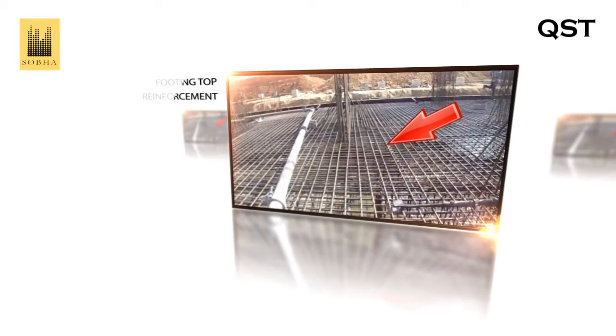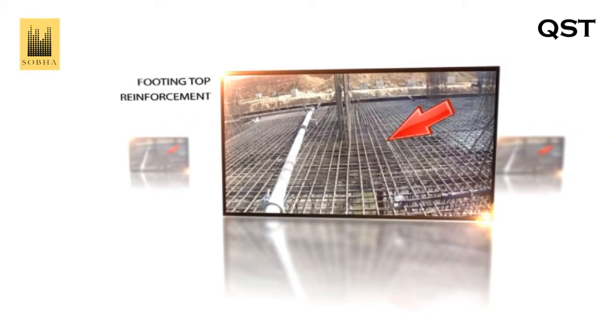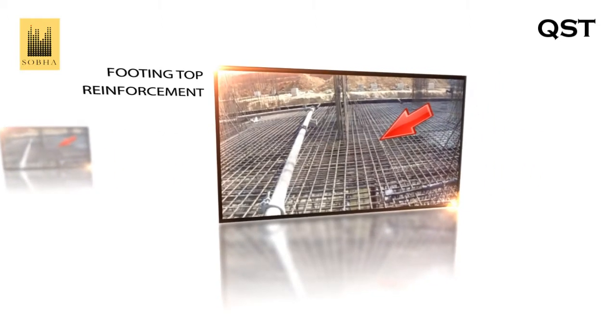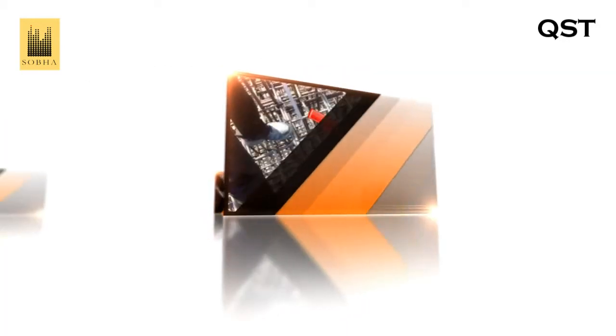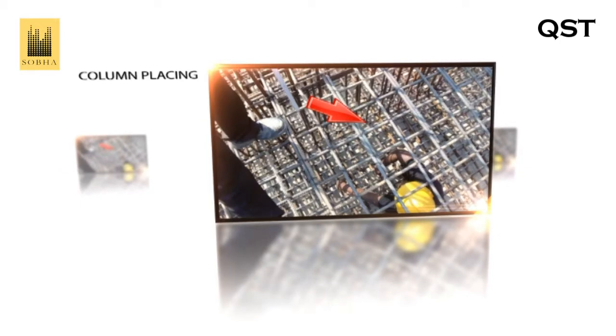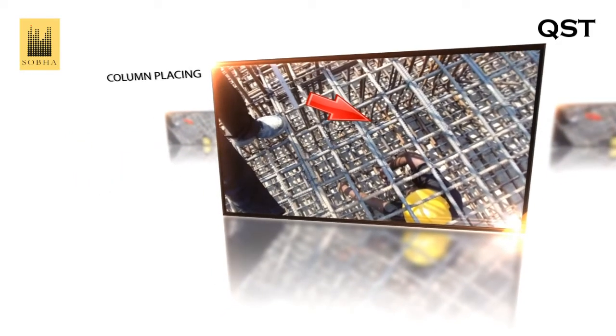Footing top mat. This image shows the typical picture of a footing top mat and additional rods. All works should be executed as per good for construction drawing. Column in footing. Column reinforcement should be placed as per column marking. Column orientation should be checked properly before concreting. Column verticality should be checked by plumb bob. Prop support to be given to maintain column verticality before concreting a footing.